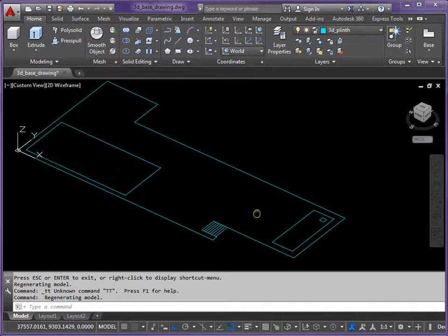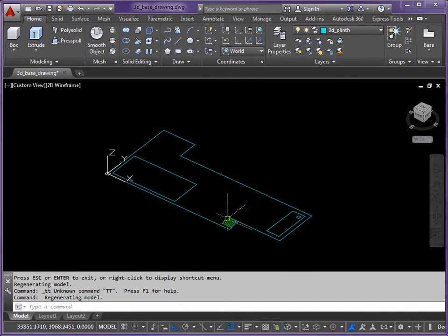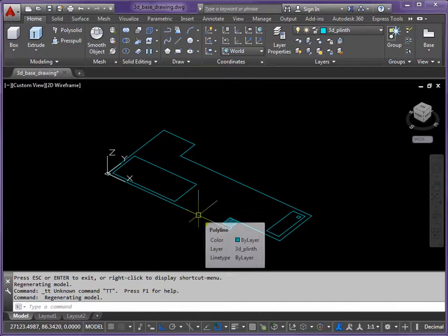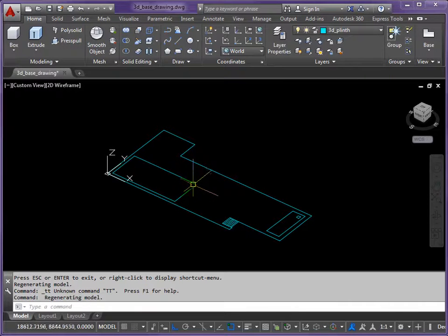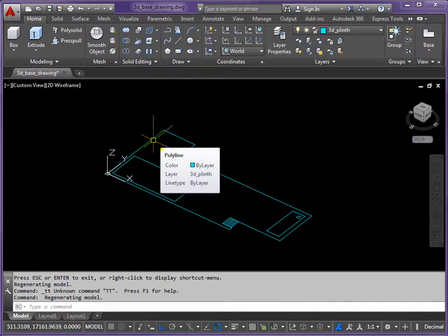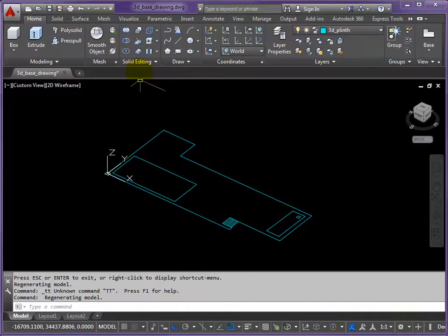Okay, so what we're going to do is firstly extrude this outer shape, and this will make it into one big solid. We'll lift these shapes upwards to the top of the object, and then we'll depress them in to form some pools. This model is going to be a combination of solids, 3D faces, and some lines that have been given thickness, which is a very basic way of creating a 3D surface, but it has its role.